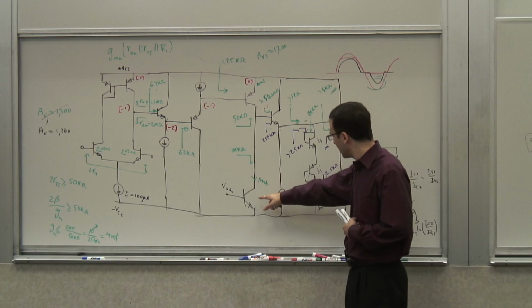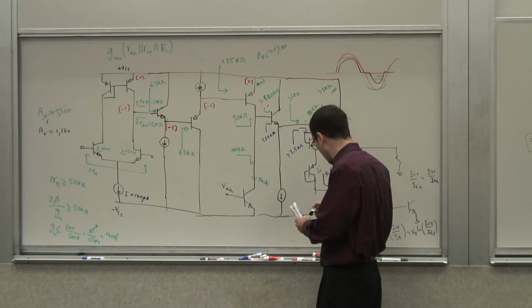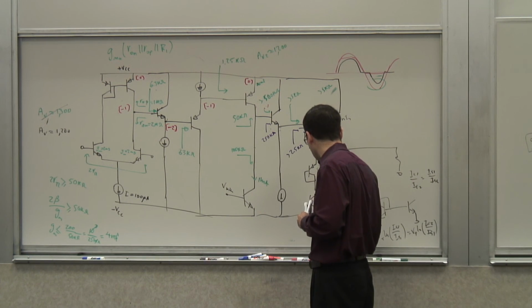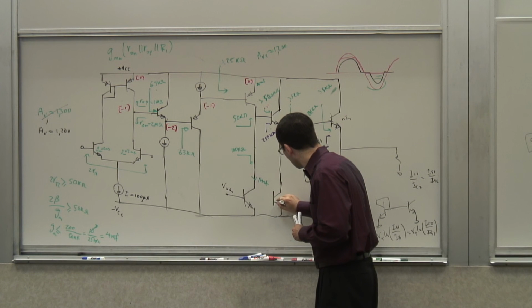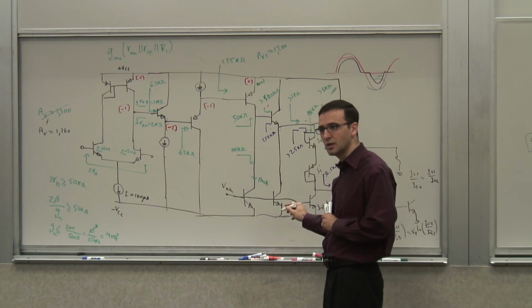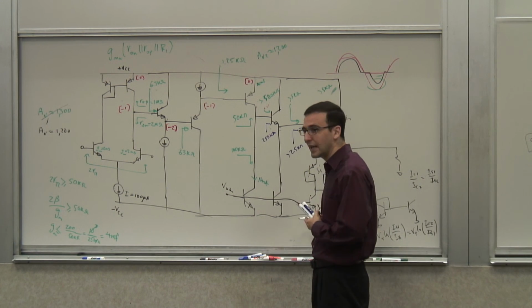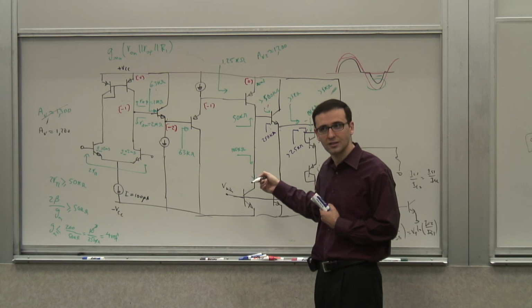Well, I know this is going to be a transistor, right? So this is going to be a transistor. So I'm going to just try to turn all of that into actual devices. And this needs to be a transistor. This is a current source, right? So these could all be biased from the same branch, right? But they have to have different values of IS. They have to be different sizes to adjust to generate the right current level.